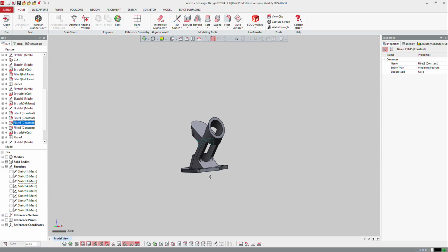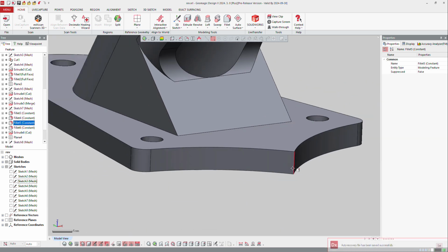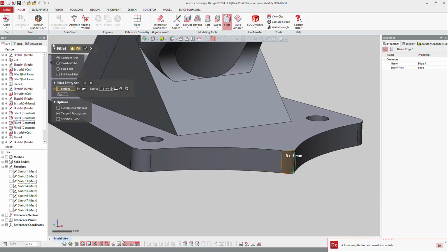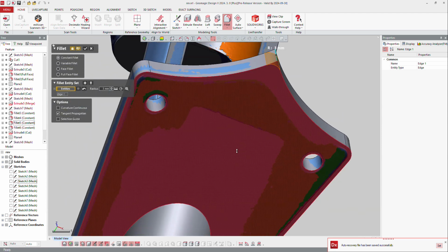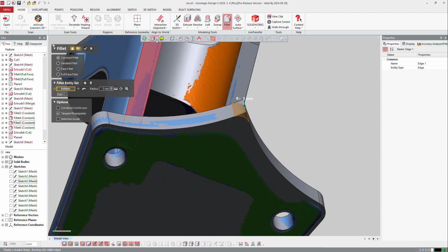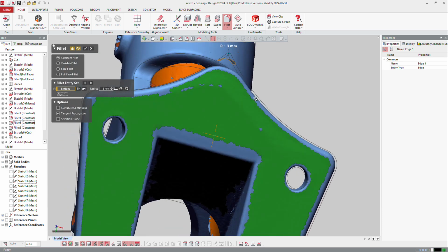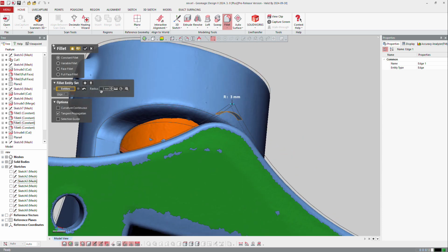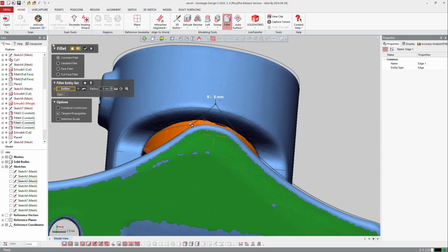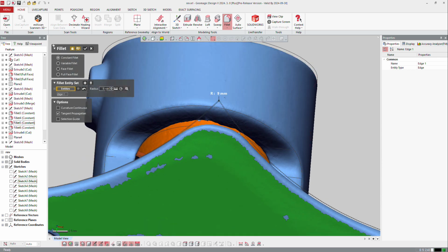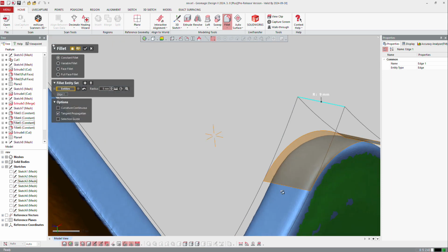Now, as at the beginning, I said I want to make that edge at the end, right mouse click here, fillet. I can always display that shape and ask the software to display my CAD in transparency here, and I can see now the fillet. I can estimate the fillet. The software will try to find a good value, so 7.6, maybe a little bit more, 7.8 or 8 millimeters. So the software always try to get a good value, but it's better when you have regions, so maybe a little bit more. 9 should be okay.